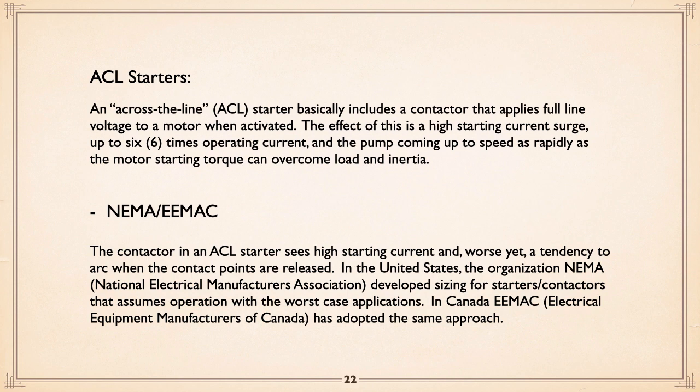Now, further with starters, there are 2 different ways of rating them, depending on the standard. Appreciate that a contactor and an across-the-line starter do see high starting current. And when it opens, with the opening of the contact points, after you turn the motor off, it tends to want to strike an arc. So across-the-line starters do see fairly heavy use.